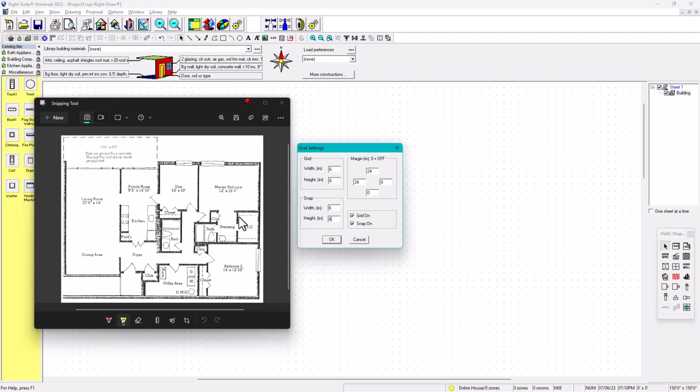And what's the reason for that? Because there are some dimensions that say 15 feet 7 inches. So in that case we're going to make it like 15 feet 6 inches, right? Or in this case, for example, we have 9 feet 5 inches, right? In that case we're just going to make it 9 feet 6 inches, or this 14 feet 10 inches. So in that case we're going to make it 15 feet. So we're just going to have that level of accuracy. One time, so look at this. This is 27 feet 6 inches, so that's perfect.